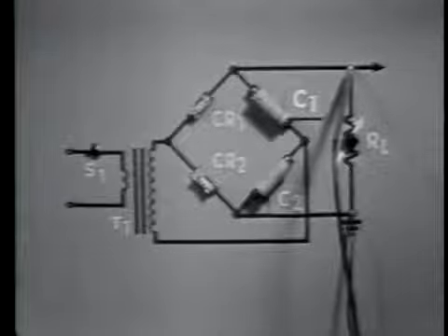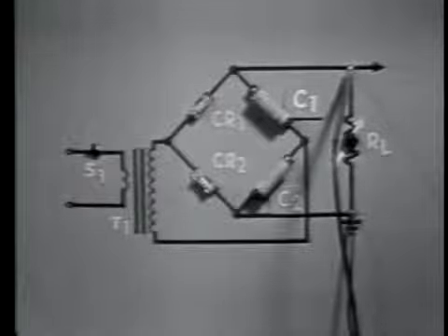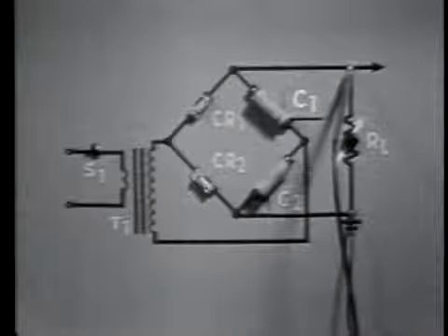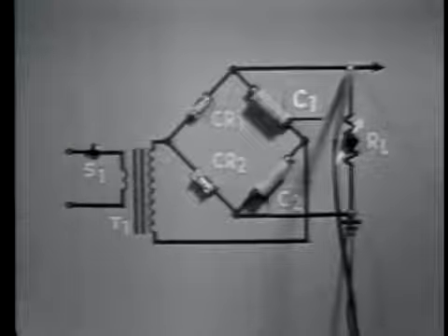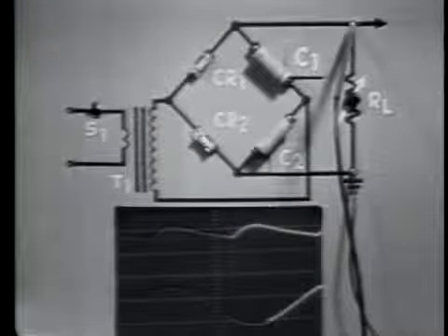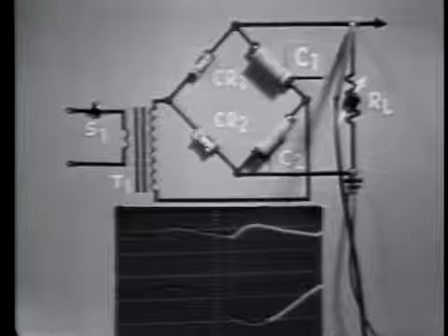Now, let's determine the effects that the load has on the voltage doubler. The effect of a load change on the output voltage can be demonstrated quite effectively using this circuit. The load resistance, represented by the variable resistor, is now at maximum resistance. Therefore, output voltage is maximum for this resistance, and output current would be minimum.